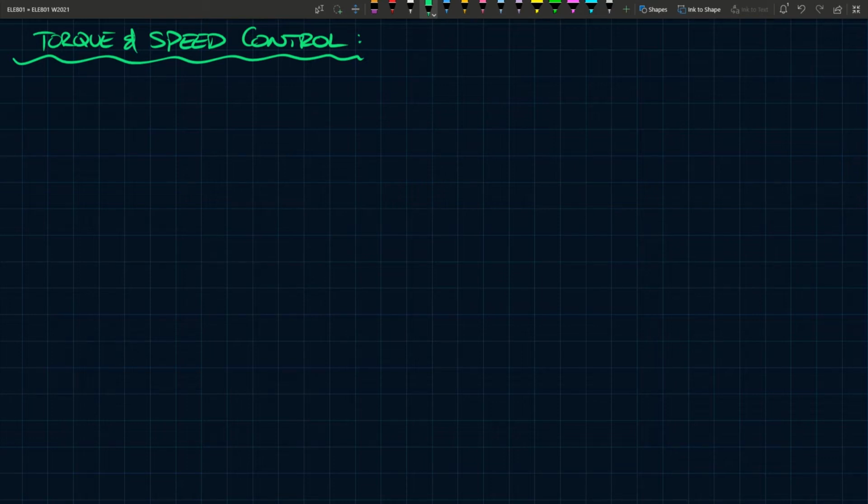Now before I continue, I should mention that every variable you see with the subscript B in this video and onwards, I should say, I guess this applies for everything, is the rated version of that value. For instance, if you see omega B, it's the rated shaft speed. If you see TMB, that's the rated shaft torque. Because we're going to start working with ratings, because now we have to consider practical systems versus just some conceptual ideal type of situation. So now we'll have ratings, and we'll have to consider operating points as certain percentages of ratings. But more on that later.